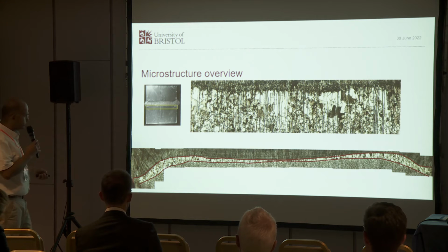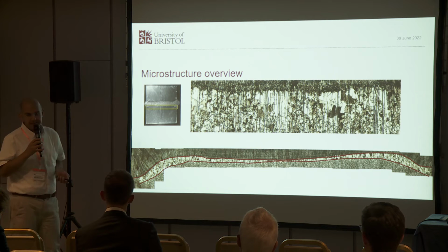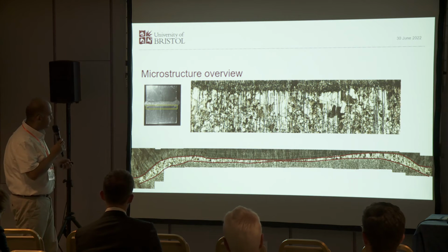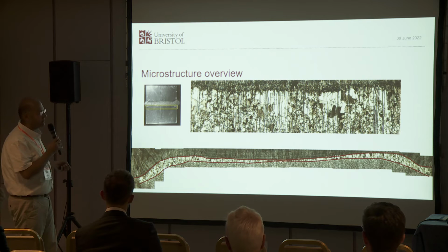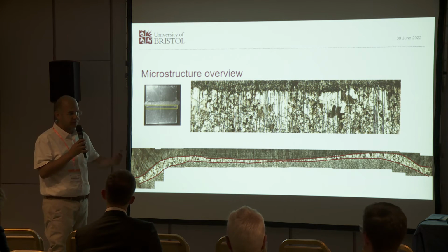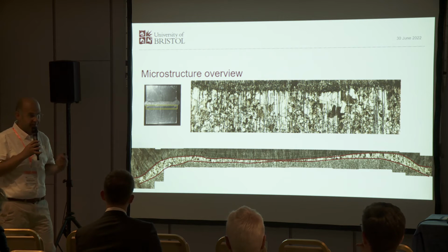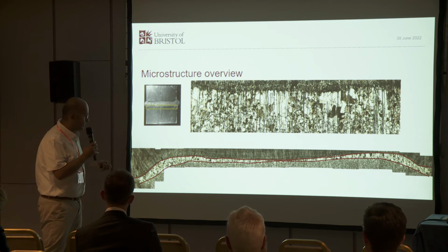This is how the residual stress, the weld microstructure looks like. This is a complete mess. It was a relatively nice ferritic material, and you get a torch to it, you melt it, you solidify it, you do it over and over again, you end up with a mess. So this mess has a lot more variability than the original plate.